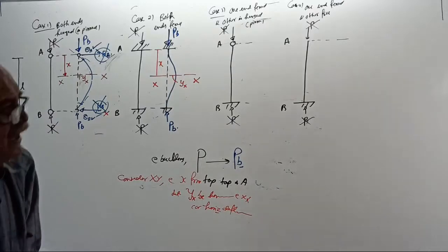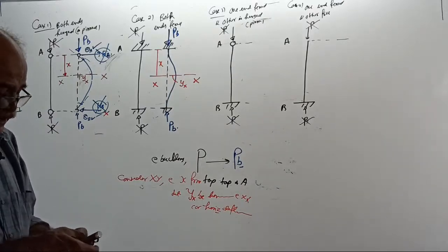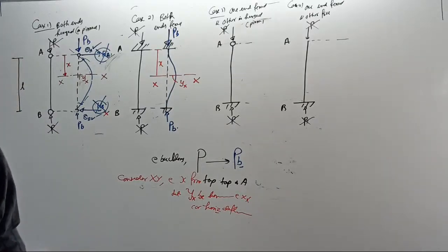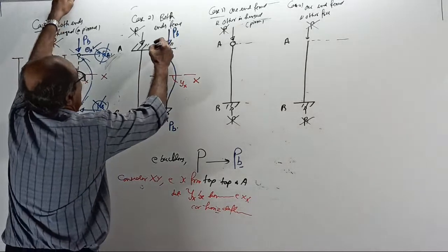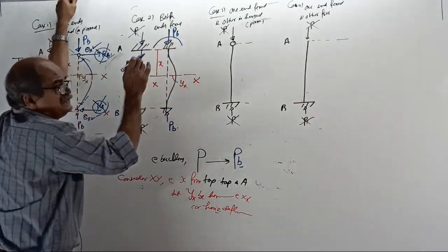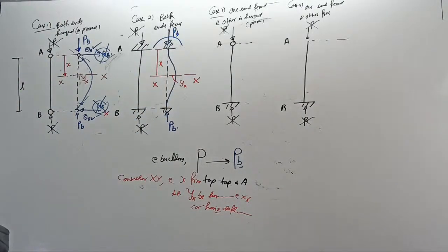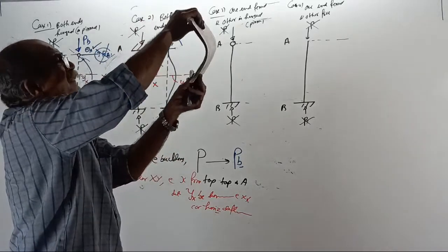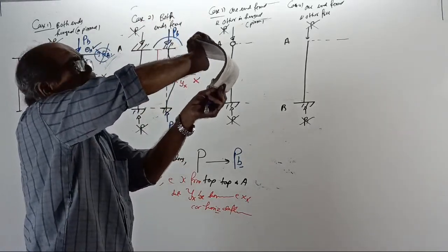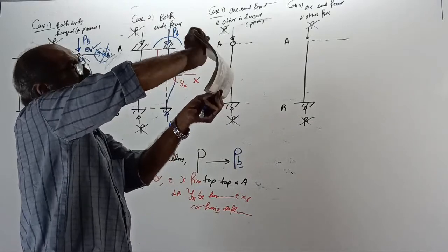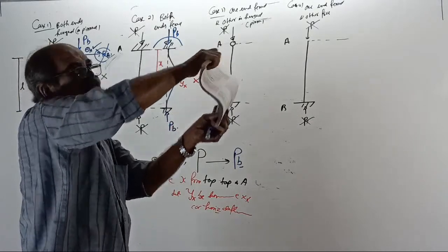No horizontal reaction, still no horizontal reaction. You tell me, there will be a reacting moment here. Common sense will tell you. See, how is the reacting moment? See here now. Buckling this way. This is pinned end, fixed end. See, it will give reacting moment like this. How? Tell me.